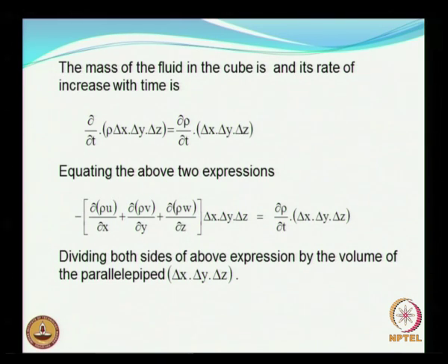Now we need to equate, in order to have the conservation law satisfied, this with the earlier expression, which is now going to be written as this, that is a summation of the net mass that has remained in the cube, considering all the 6 faces, I mean 3 pairs of faces. So now this is the final expression which we have arrived at. Now divide both sides of the above expression by the volume.